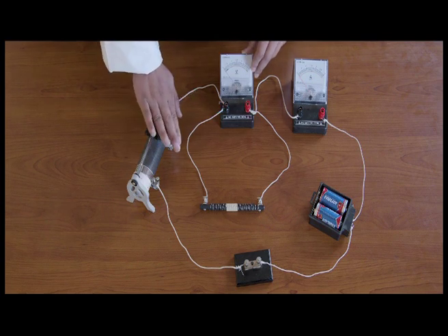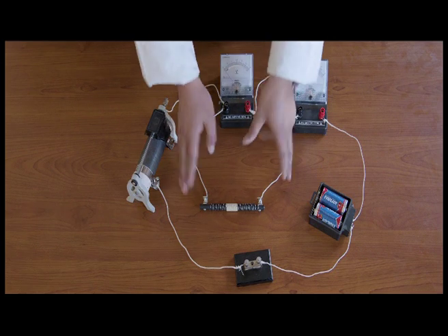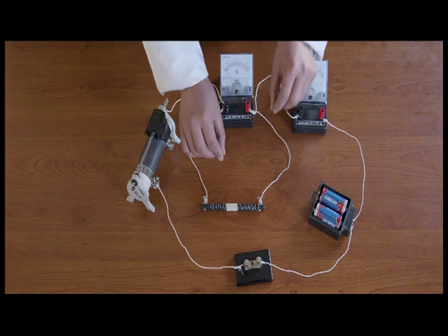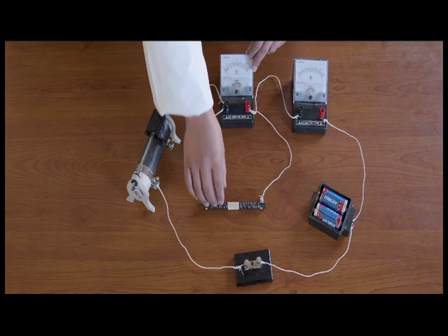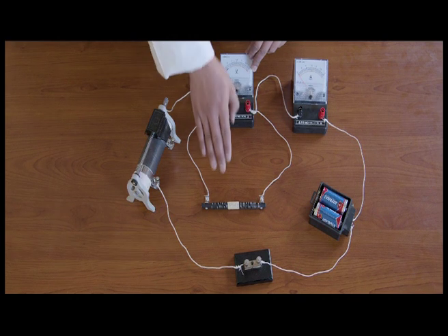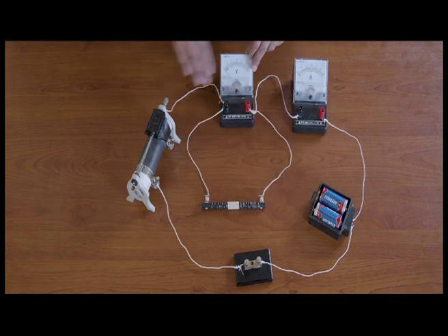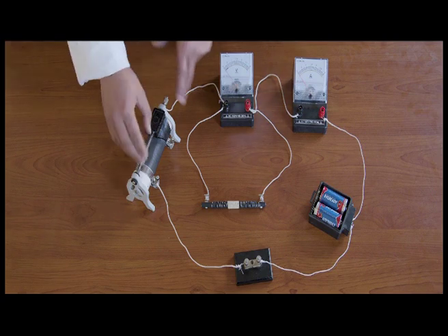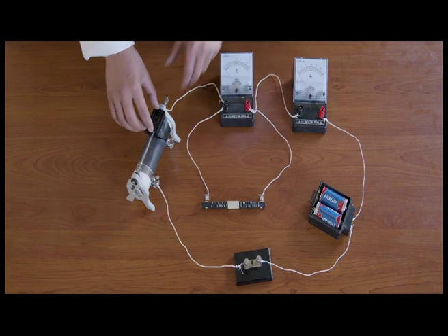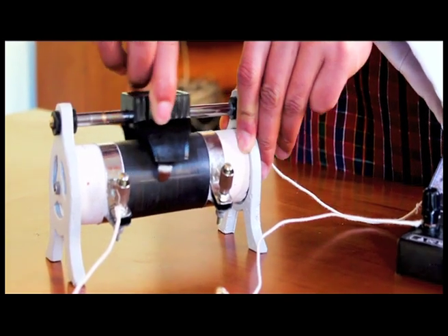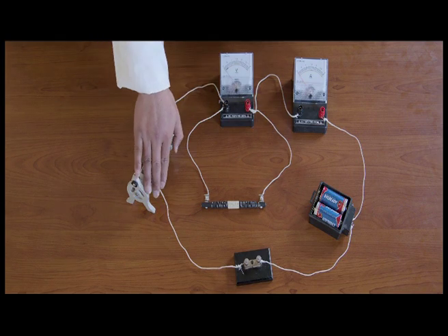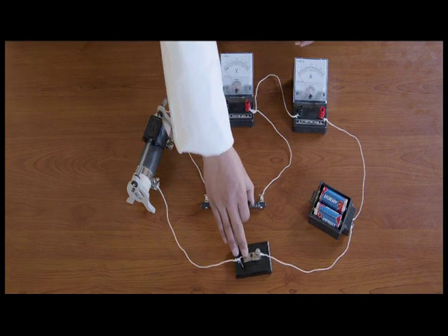Before I talk about the function of the rheostat, you may be wondering what this particular thing is. So here I am connecting a resistance, a 50 centimeter metallic wire, parallel to the voltmeter. So this will provide the resistance to the flow of current. Now this device is a rheostat, and the function of the rheostat here is to regulate the amount of current flowing in the circuit. So I can shift this in different directions to adjust the amount of current flowing through the circuit. From the lower terminal of the rheostat, it's connected to the first end of the key.